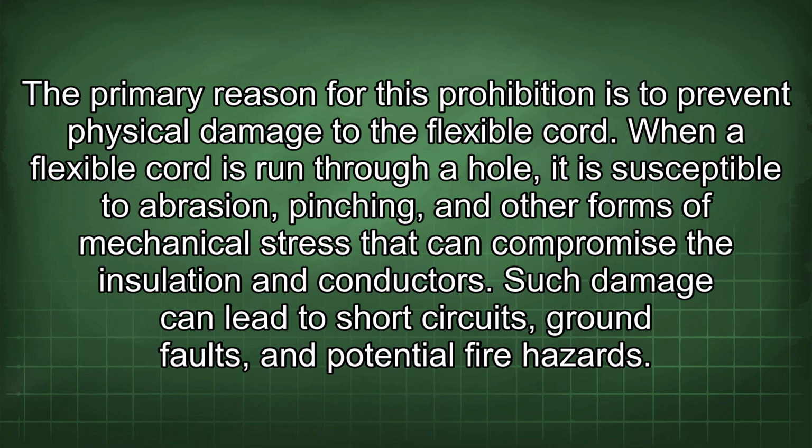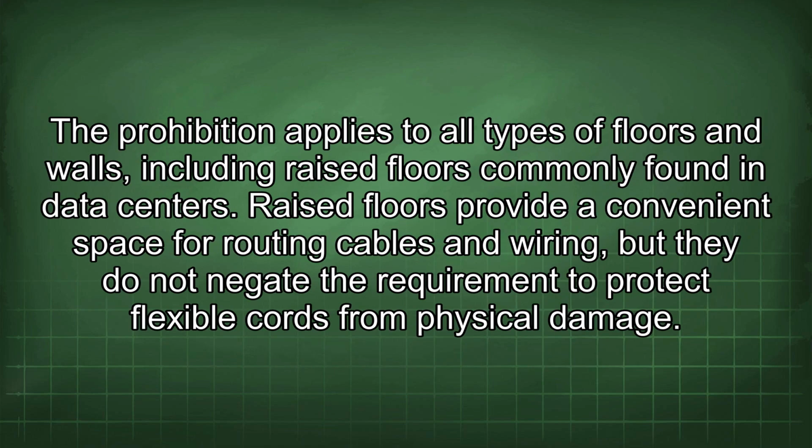Such damage can lead to short circuits, ground faults, and potential fire hazards. The prohibition applies to all types of floors and walls, including raised floors commonly found in data centers. Raised floors provide a convenient space for routing cables and wiring, but they do not negate the requirement to protect flexible cords from physical damage.